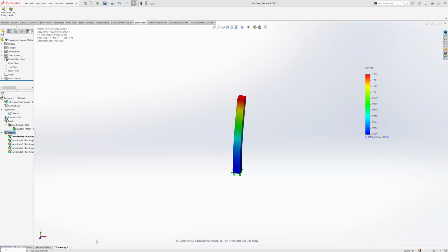I'm going to have to stop sharing real quick, because this is one thing I have actually noticed with SolidWorks. There's my plot. You can see my plot, right? Okay, perfect. So with this plot, make sure you don't just click on the screen. Make sure you close the plot, because when you click on the screen, it goes in the background, and then everything else in SolidWorks is frozen. So you run into that problem. Just get used to closing this.